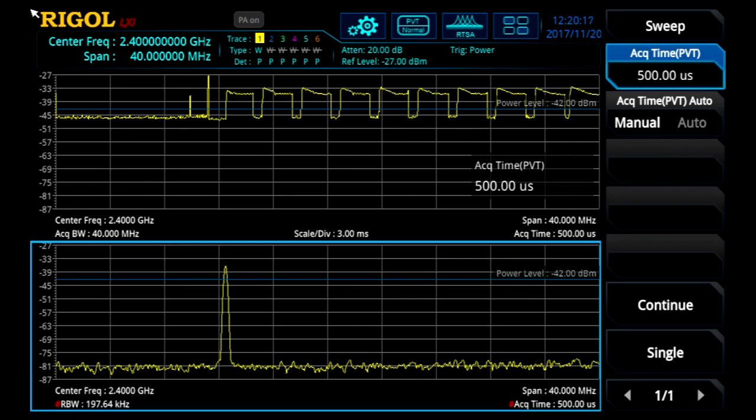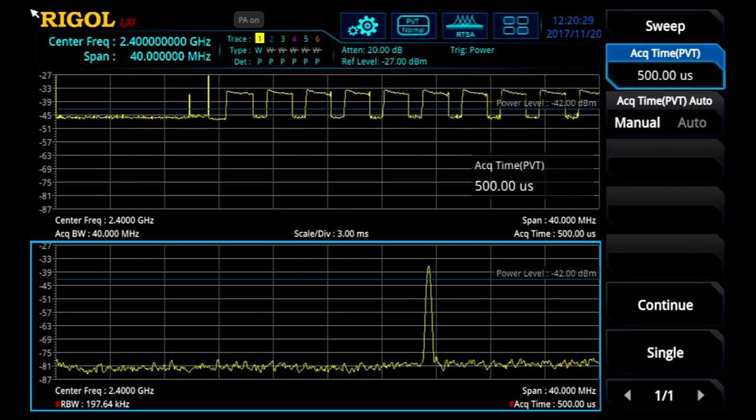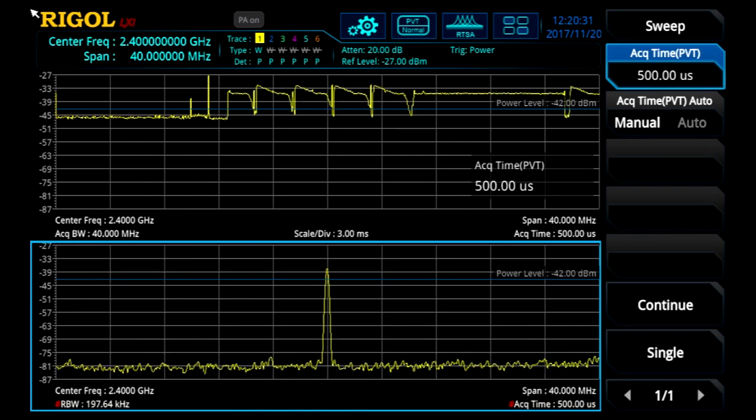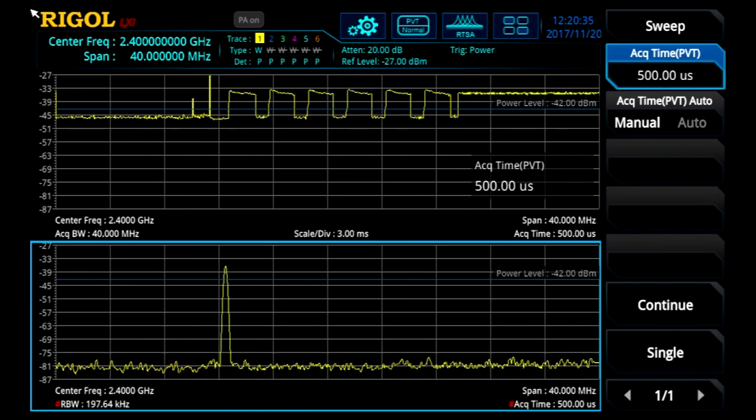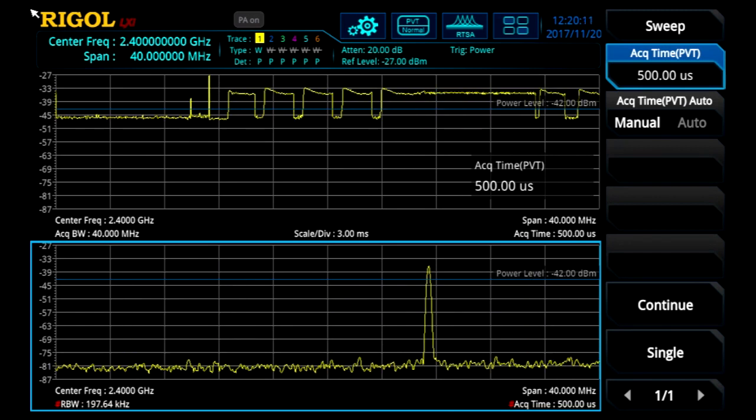We trigger on this change in power to view the modulation in time, even as the carrier changes across the span below. Now we can trigger on power in the time domain, giving engineers one more way to identify the transmission they are looking for, while still seeing it in the context of the entire RF capture.